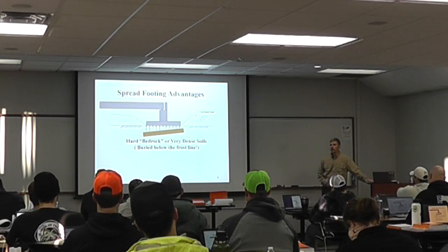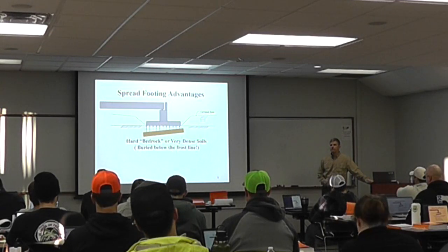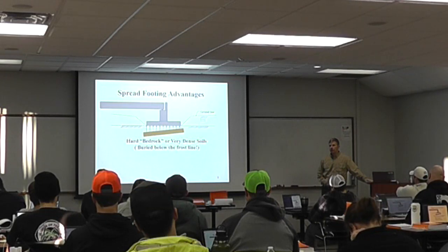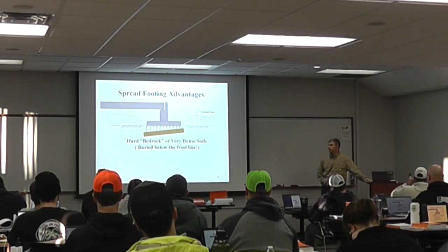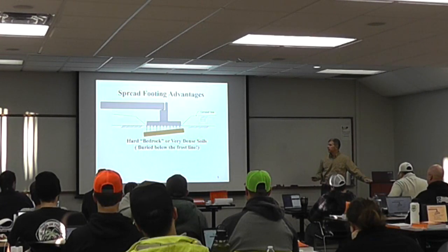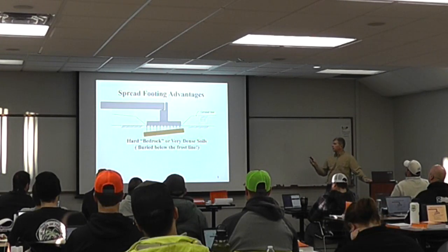Stability. Why? You're not driven deep into the ground. And so if the upper soils are soft, what might happen? Could tilt, sink, settle. Yeah. So here's some pictures of some of the things.